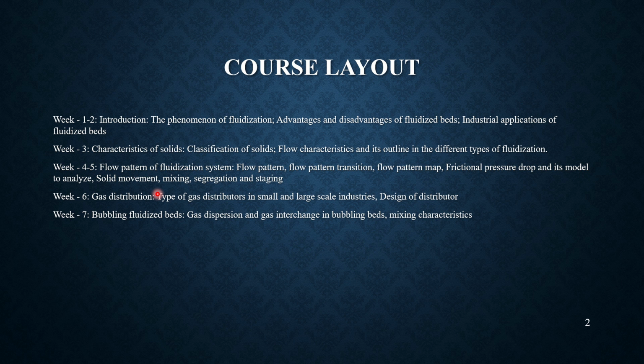And week 7 we dealt with bubbling fluidized beds. Again, in bubbling fluidized beds, by now we know that it is very important to study, and we must be in a position to predict what is happening inside the bubbling fluidized beds. So in terms of gas dispersion and gas interchange, mixing characteristics, because those bubbles only carry a certain amount of solids with them in the form of wake, and once they reach the surface of the bed, they again throw the solids inside the bed. So solid circulation in turn happens by using this, and depending on the binary, if two or more components are present, the fluid velocity range should be adjusted accordingly, such that we would be obtaining mixing or segregation, whatever is essential.